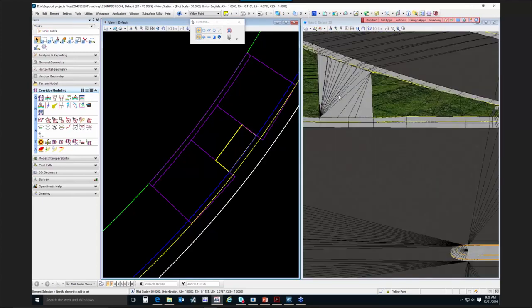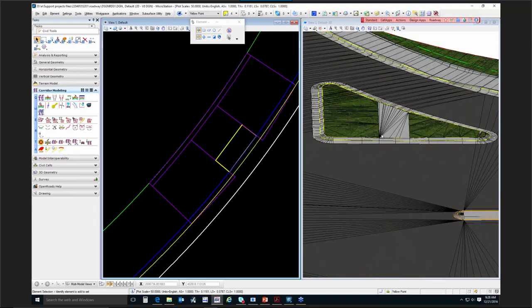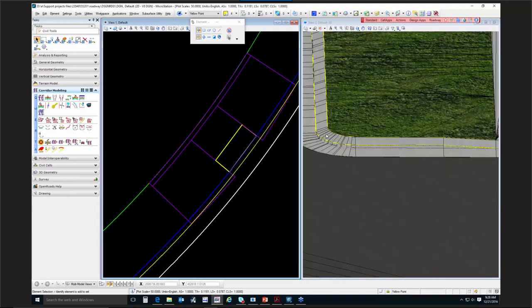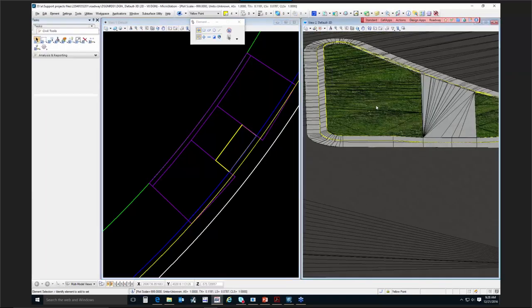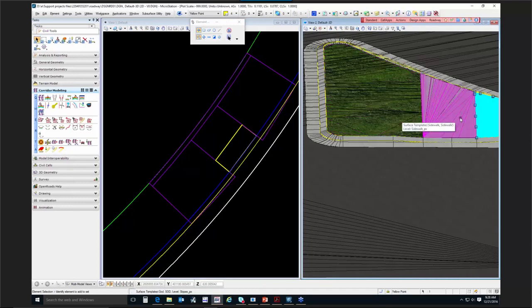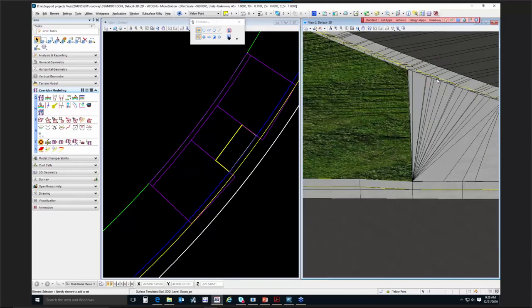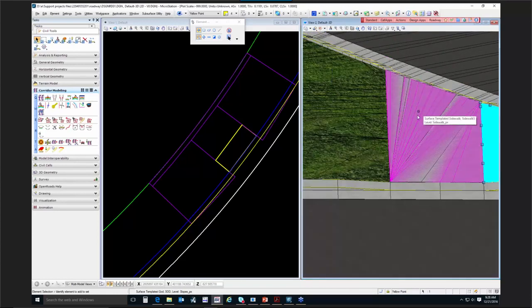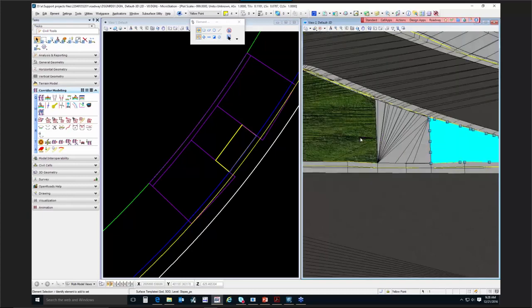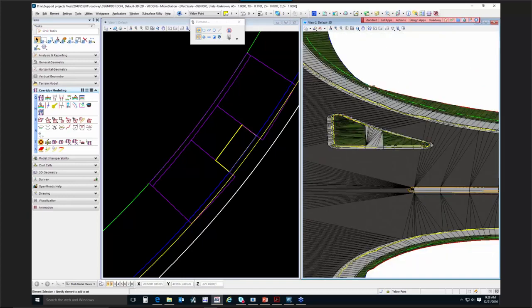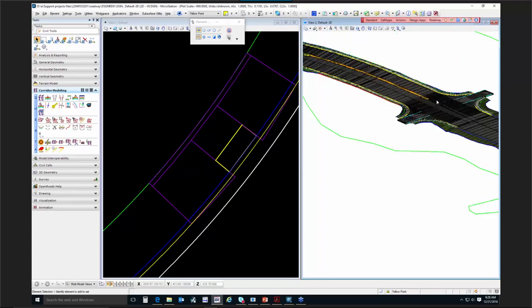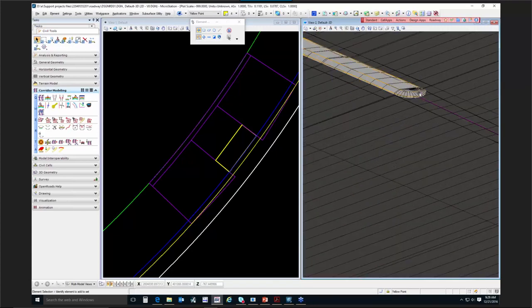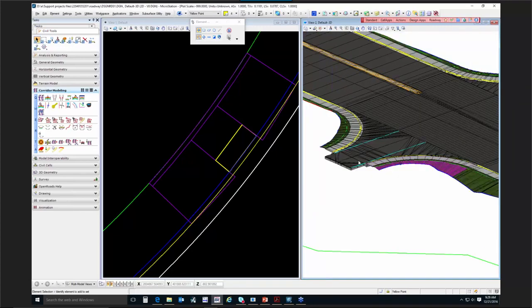Things like islands. This island here has got a sidewalk across it, so you got sod here on one side, sod on the other, and then concrete in the middle. And that concrete has a thickness, and when we're thinking about quantities, we want to make sure that we're transitioning down and adding the specific details in the model for that. A lot of it's pretty tedious, but it's what we need to move to for modeling. So you can see some of the examples we're talking about.